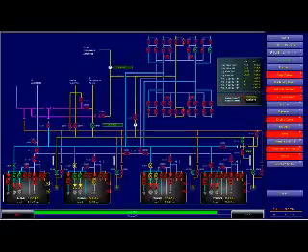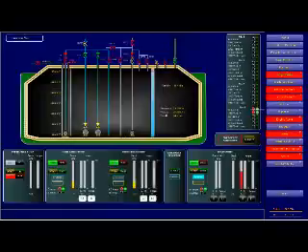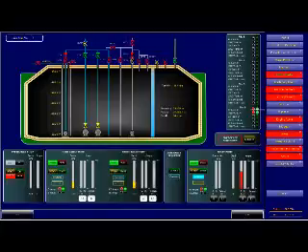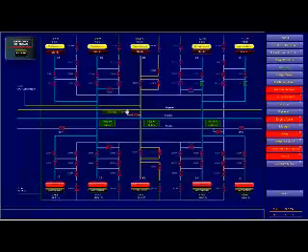So, I don't know what alarm this is. Which one? Cargo high tank pressure. So maybe the tank pressure has gone up and the relief valve is open. But this should not be blinking once you put it. So keep this line open, and open the manifold valve and give the vapor to the shore, so release the pressure. Because you are not consuming in the engine, that is why the pressure is building. So open the valve.